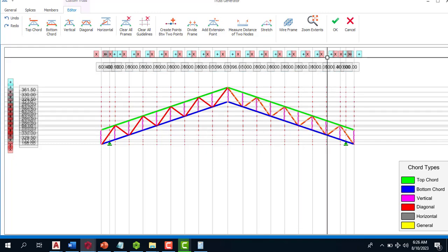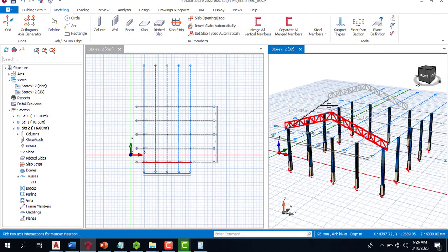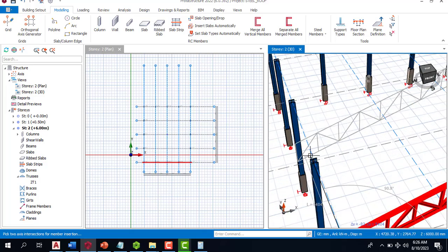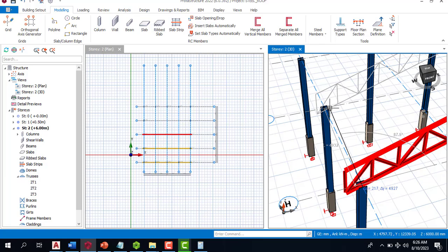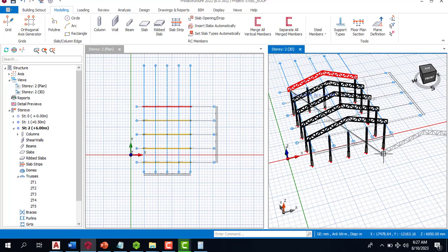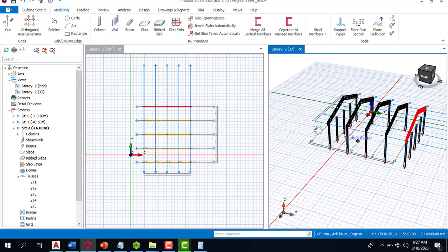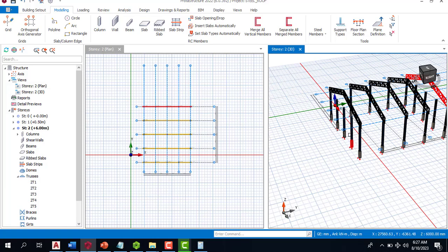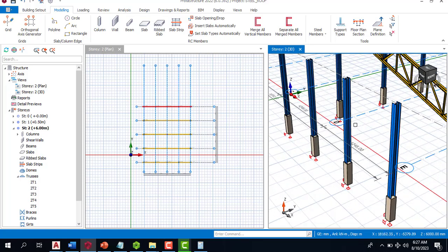Okay, so right now I'm going to click on OK. You can see that has been created automatically for me. I can just rotate this and place them everywhere I want them to be. So irrespective of your steel cross section, no matter how they come, you can simply create it from your AutoCAD and import it into your Prota Structure.